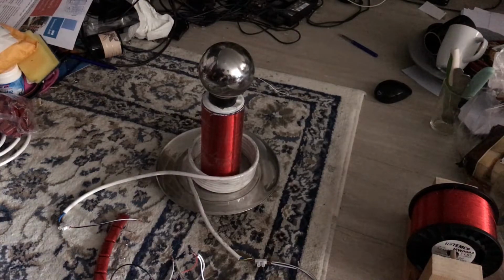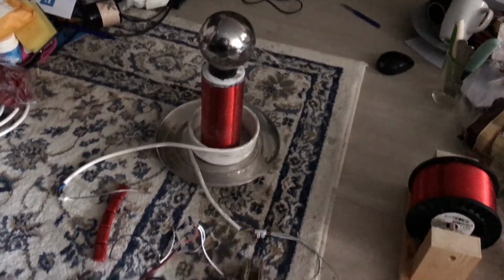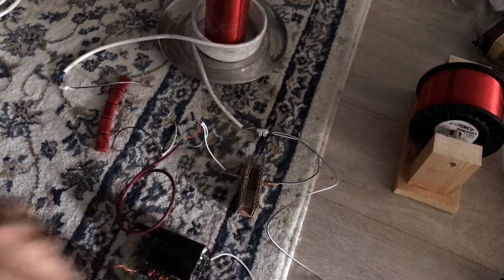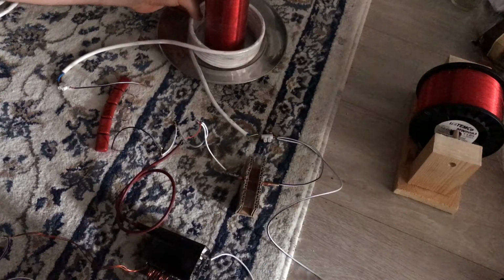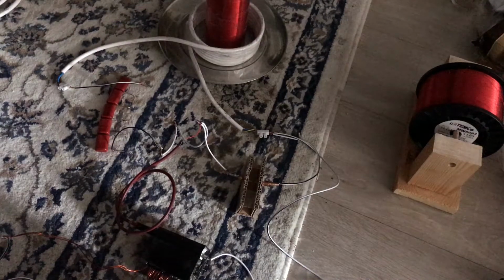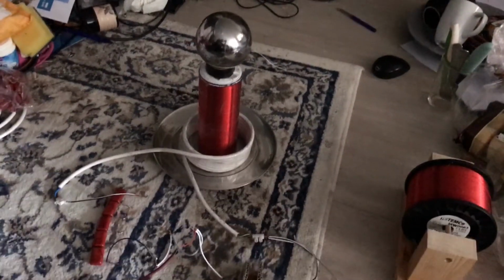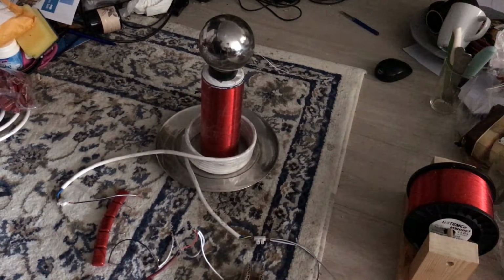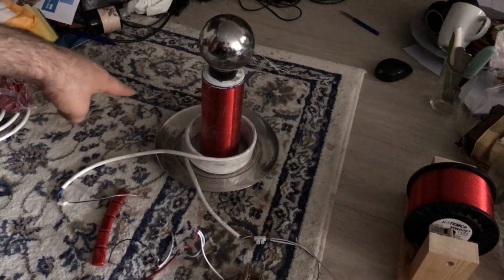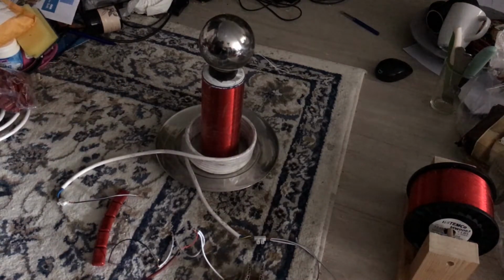Now, because here I do not have discharging resistor for this capacitor, you have to always discharge this spark gap. So here I discharge. And now I put this coil like in the center. Okay, so now let us look at the discharges again. But you may notice on the back side still we have discharges to the primary coil.